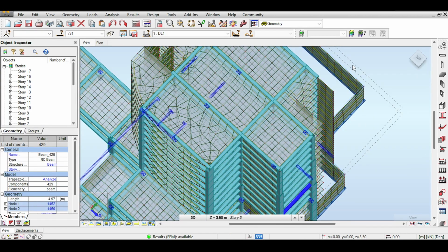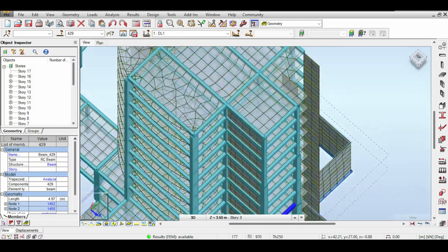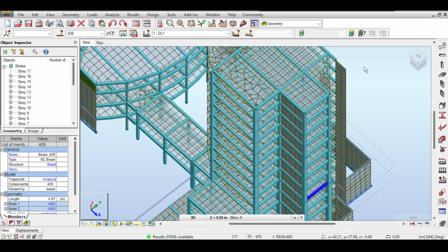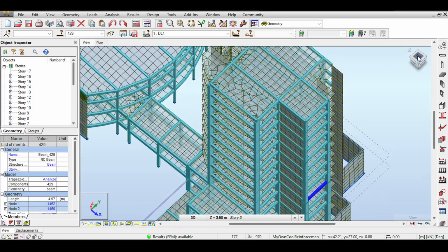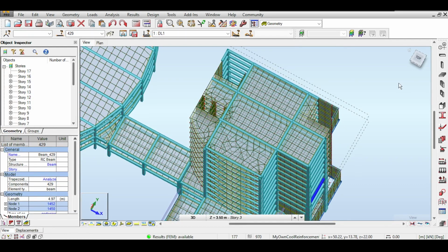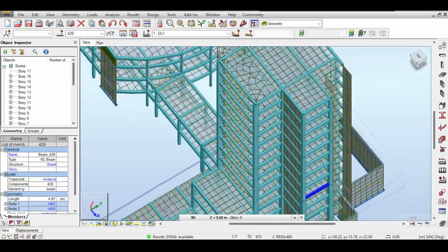Okay, so you can see that the problem has gotten less, and the situation has improved by reducing the lateral deflections, as well as reducing the twisting, and as well as reducing the relative displacement of the structure from each story to the other. So at least now we know exactly how we would do that.